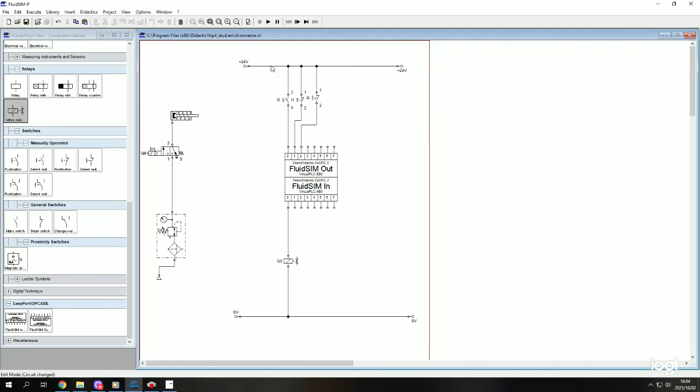So we were able to still use a spring return cylinder with a solenoid valve that has a spring return, and we were still able to achieve a latching circuit. We were still able to advance our piston rod without automatically retracting it by means of a spring return effect. So there are many ways of developing a circuit to fulfill just one process or purpose.